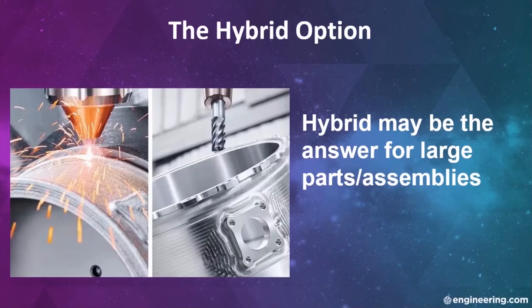Another advantage of a hybrid is G-code commonality. Operations designed for machine parts that need very specific, complex external attributes can get them without introducing additive as a new process into an existing workflow. This is a real advantage for customers who need certification of their processes as well as their parts, and that institutional knowledge that they already have from machining carries over directly.